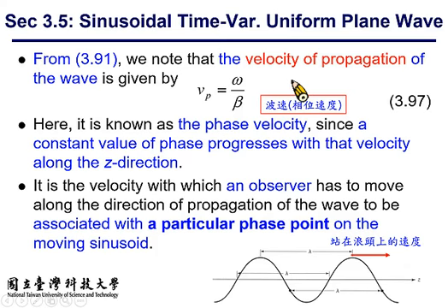The 3 times 10 to the 8th, the speed of light, is actually the lowest phase velocity of electromagnetic wave propagation in free space. If you are looking sideways, not along the actual propagation direction, you will end up with a higher phase velocity.